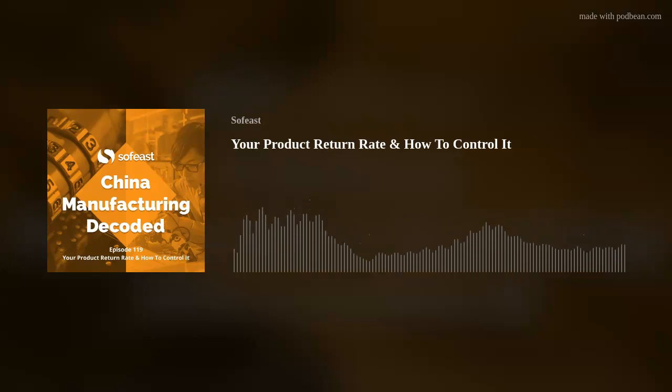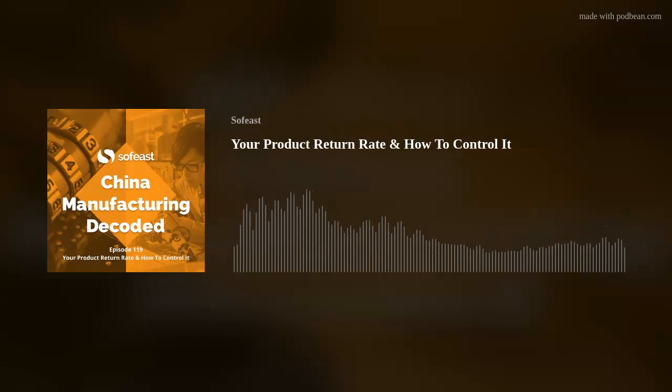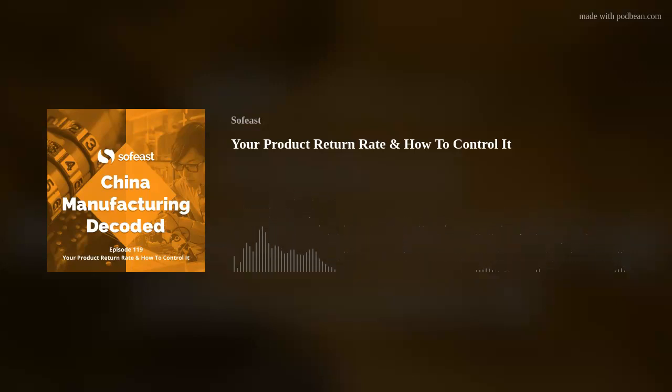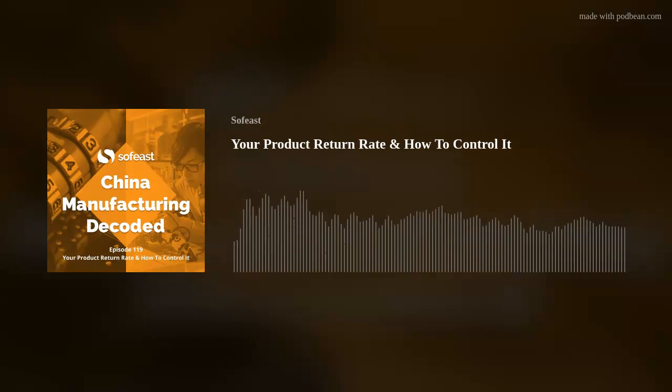If your design says that this is going to be operational between, let's say, 0 and 70 degrees Fahrenheit, I mean Celsius, then you want to make sure that your component is going to be able to handle a little bit colder than 0 degrees and a little bit warmer than 70 degrees, so that if there's a fluctuation in the temperature alone, the component can still handle it. Yeah, that makes a lot of sense.